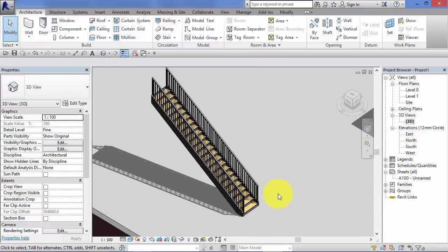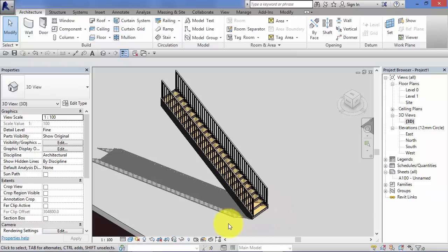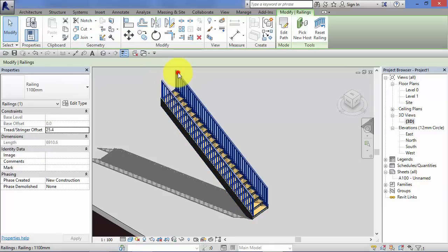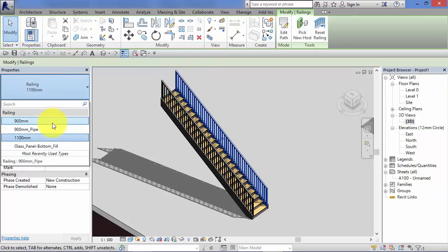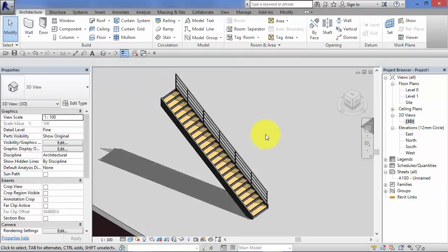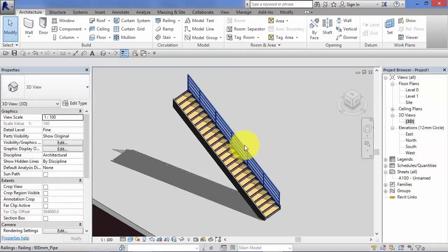The thing to note before we move on is that in that operation Revit created the stair run. It also created handrails, but it created these as separate elements in their own right and separate on left to right as well. So you can go and change their types individually or both. You can delete one or both of those handrails if you don't need them. In a separate unit we'll look in depth at handrails in Revit and their creation and manipulation.